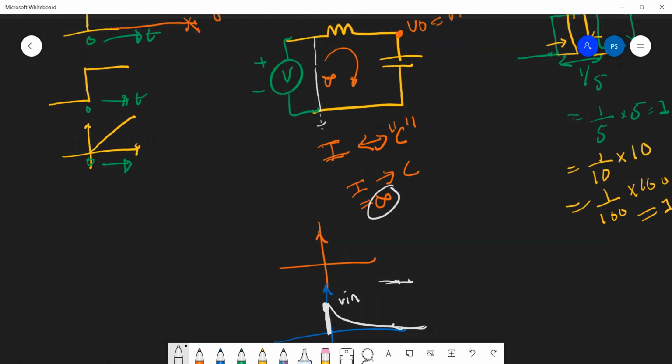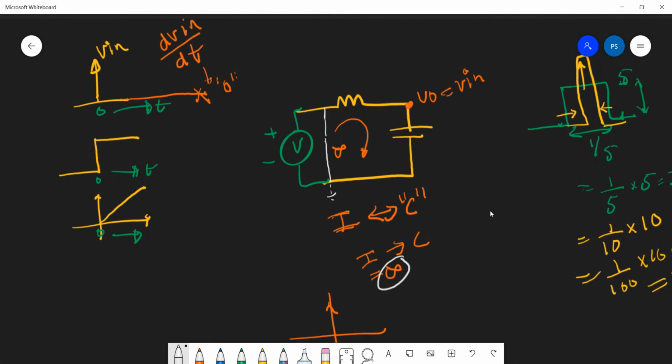So this is about the impulse response. These two points are very important. The capacitor charges only when the current is infinity, and that happens when you give an impulse. And for an impulse, the capacitor charges instantaneously to V in, or whatever voltage you apply here, and then after you remove that, after a very long time, it will settle to 0. It will discharge. So this is the impulse response. Now we apply the same logic to this case.